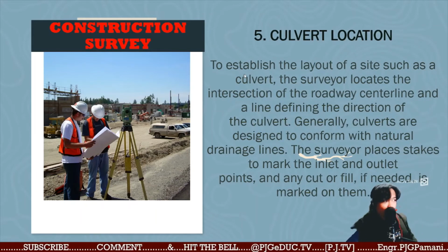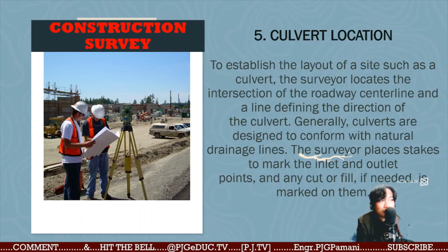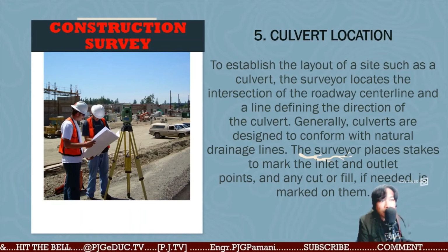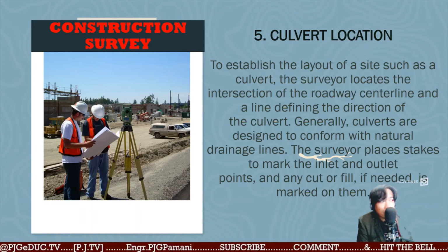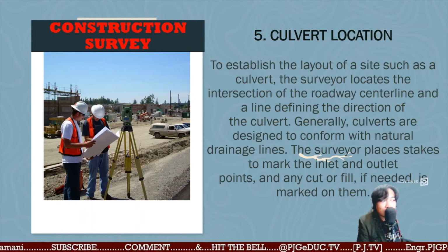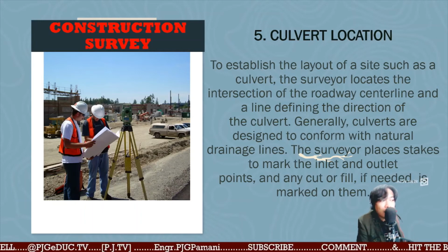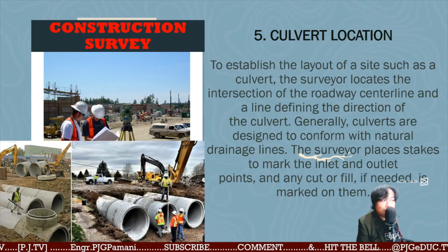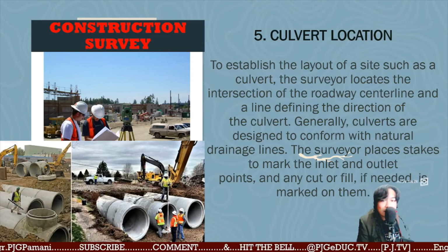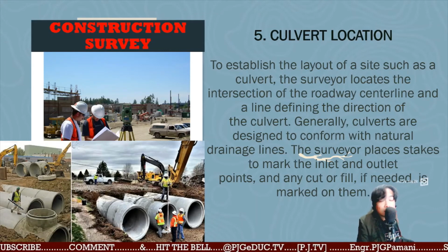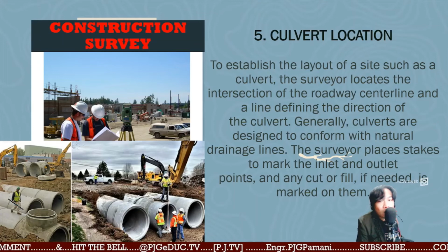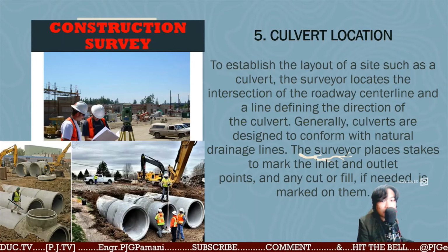Then we have the culvert location. Very important din ito, lalo na sa mga business areas that are being traversed by these roadway constructions. For culvert location, to establish the layout of a site such as a culvert, the surveyor locates the intersection of the roadway center lines and the line defining the direction of the culvert. Generally, the culverts are designed to conform to the natural drainage lines. Part po yan lagi, lalo na kung ang roadway build-up mo is along commercial areas or business areas.